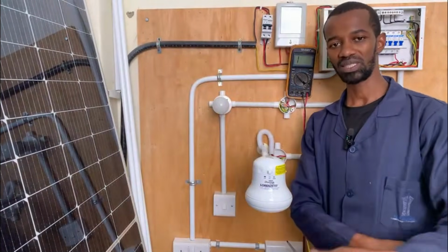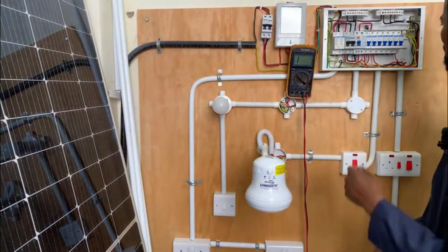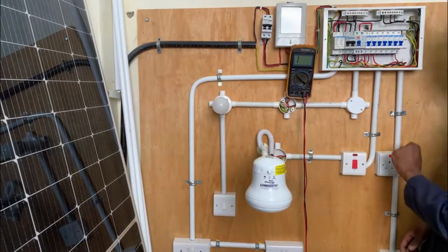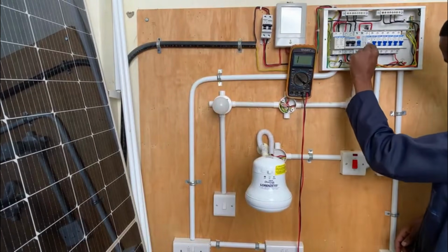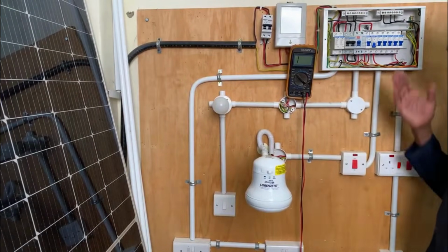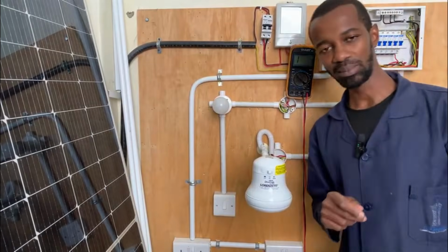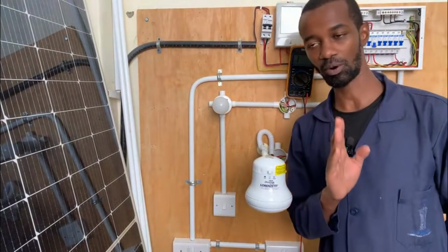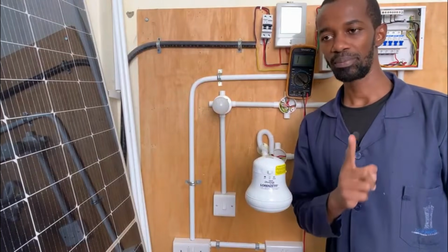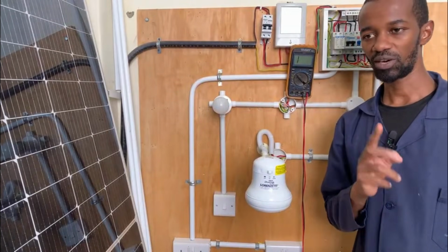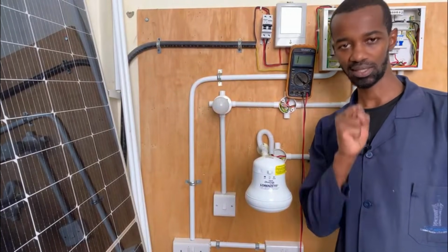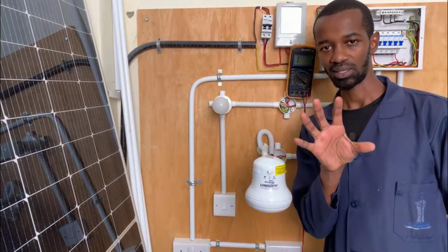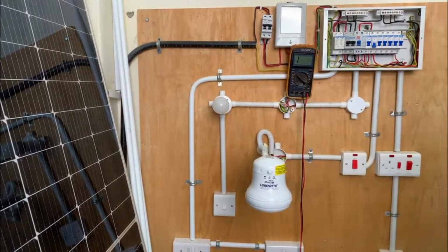So that is basically it. You go circuit by circuit. Assuming the same problem happened with this, you see, you have a cooker unit here. It is supplied by this MCB. Go to a customer and you find that there is an MCB that has tripped. In most cases, you'll find that a specific circuit has a problem. Only one MCB will have tripped. If that circuit is the one that has an issue, you now narrow down to that circuit. You ensure that you only solve it.